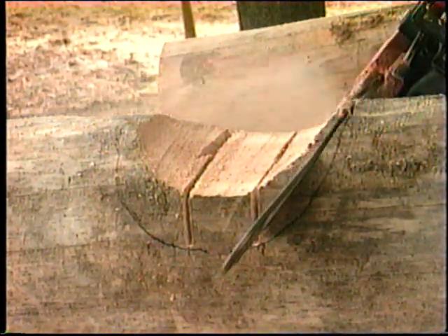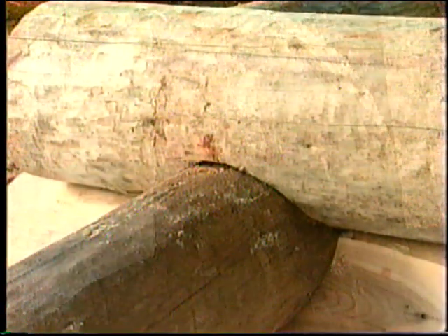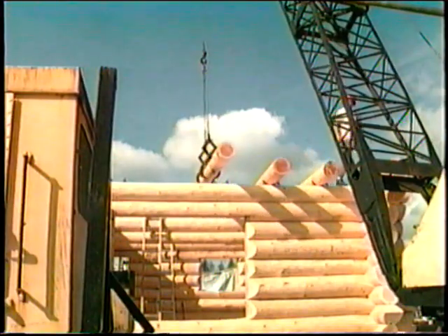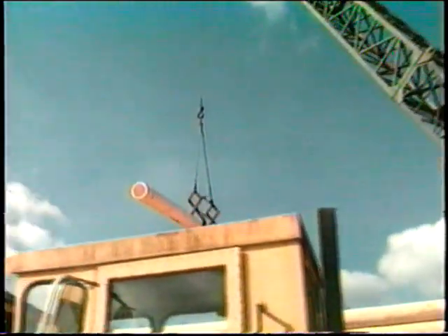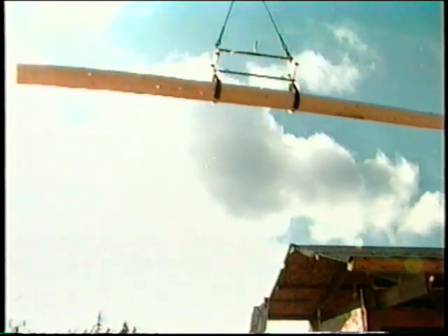Remove the joists from the building to do the cutting, and if you have suitable equipment, remove also the log on which the joist will be resting. Doing the cuts on the ground will speed up the work and increase the accuracy, but these cuts can also realistically be done up on the building.